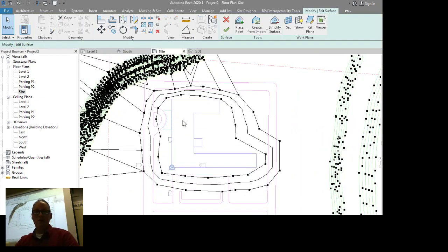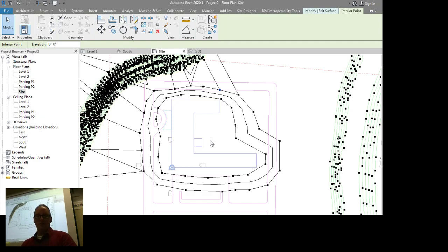Now, if you don't see what I've got on my screen here, we'll talk about some of the reasons for that presently. So what we've got is we've raised the ground 2 feet, roughly where the building is, and I've just put those points in every 20 or 30 feet or so, and that's about all the accuracy that you would need. And then I put another set of points whose height is 0. So you'll notice that when I click on those points after I've created them, that one's elevation is 0. These ones here, their value is 2 feet.